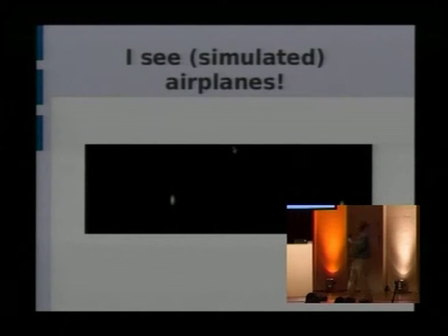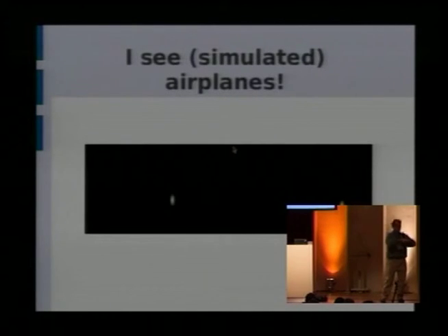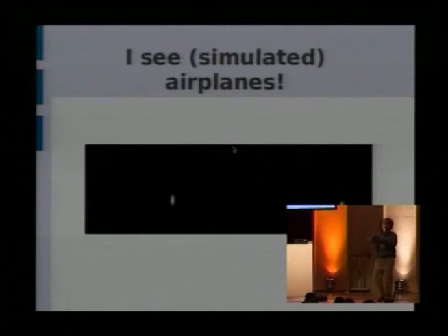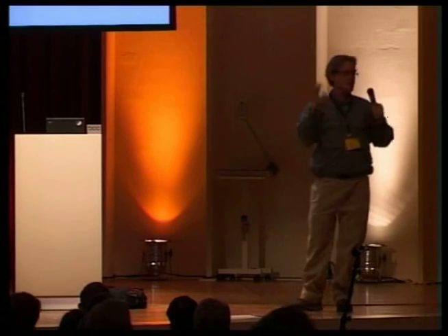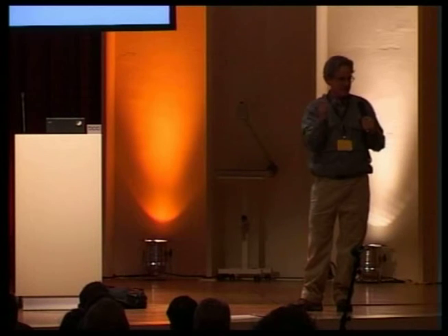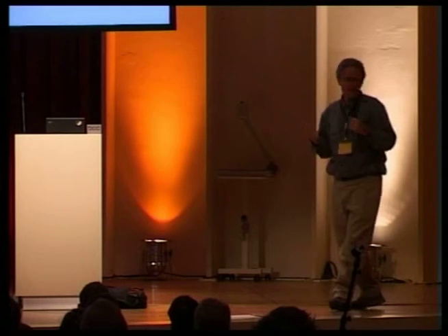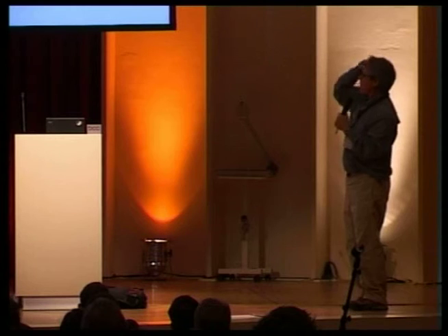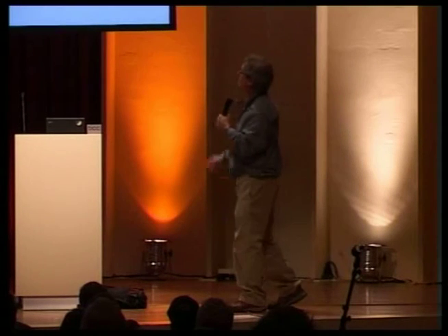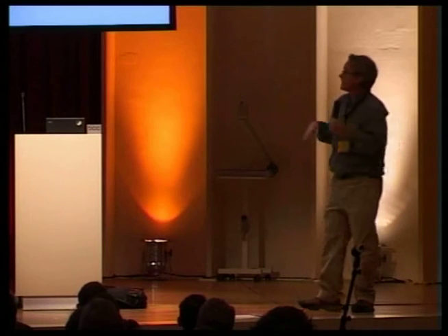But if they're really cranking it up, you have this idea that when you're trying to make this time measurement, what you're actually doing is you're correlating, you're sliding a delayed version of the signal against a non-delayed version of the signal, and it's brute force. You say, okay, try matching them up here, and you basically compute this. It's the correlation, but it's basically you take the complex conjugate and sum them. And you can pick how big a window you like, and the bigger this window gets, the tighter you fit. So since I can do a second's worth of data, it's like 250,000 samples. These ones were done with 25,000 samples here. Anyway, so you get knobs to twist on, how does it look.